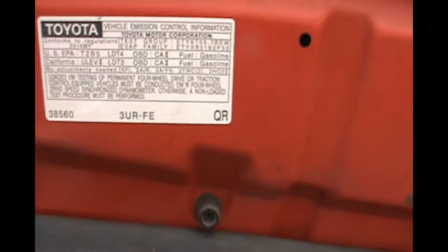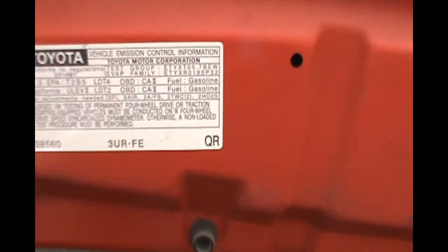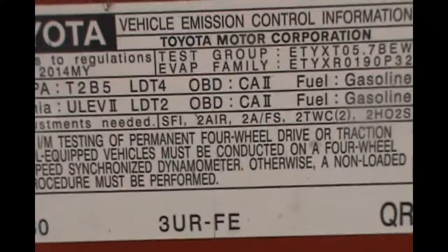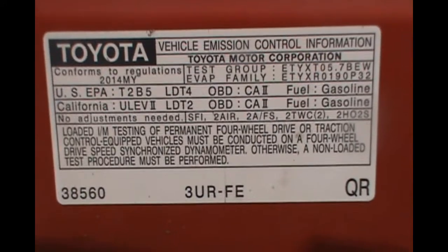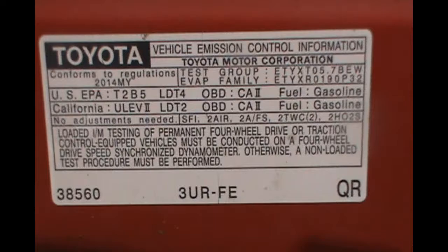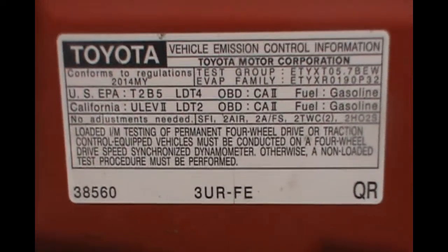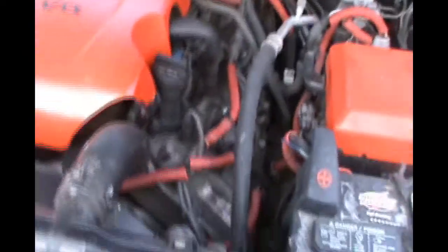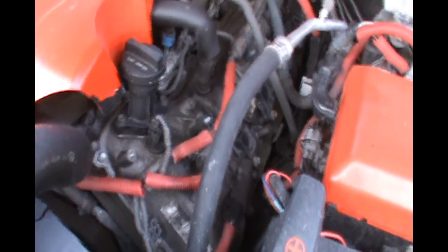And on that sticker, somewhere, it might actually have written, which a lot of vehicles do, all of the pertinent engine information. Some of them even include the spark plug gap. Now, if there is no spark plug gap included, you would have to find a service manual, or you can look it up online. This engine here, I had to look up the spark plug gap because it's not located on that sticker. And it's supposed to be at 30 to 35 thousandths of an inch.